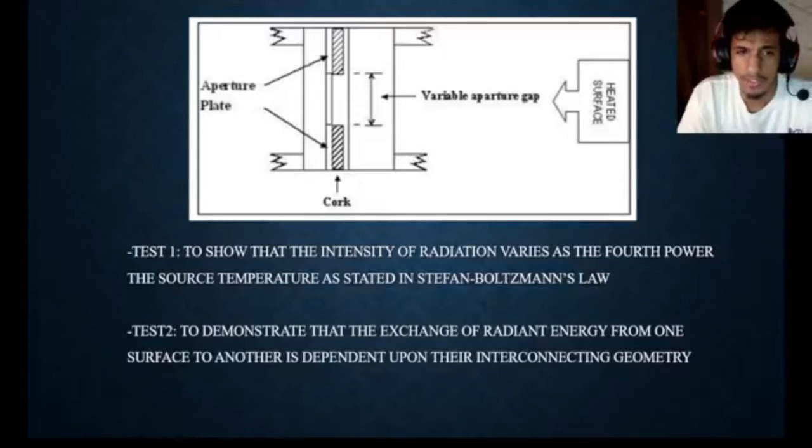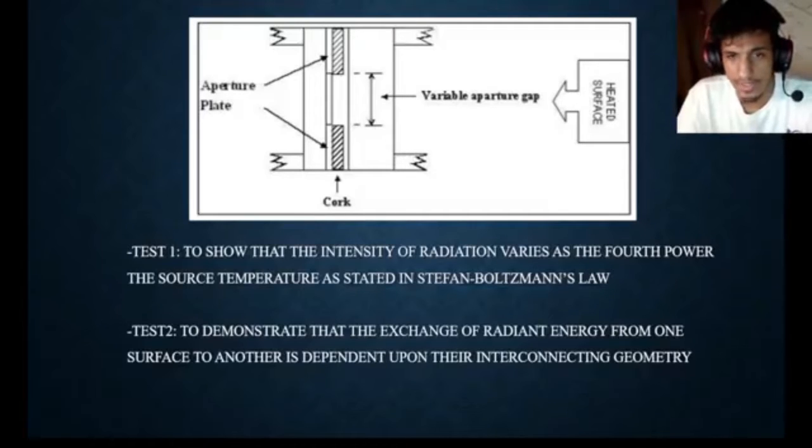So the first step is to connect one of the thermocouples of the target plates to the service unit and place the plates on the bench to record the ambient temperature. Secondly, position the radiometer on the test track at 800 mm from the heat source, and select the selector knob on the heat transfer service unit to read the radiometer measurement. Set the heater temperature to 250 Celsius by the heater controller.